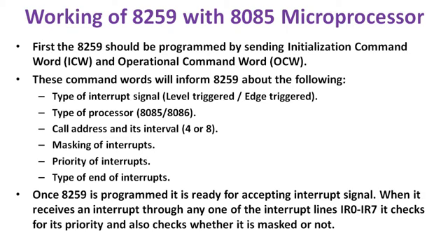And suppose IR0 is made high, then it will again check whether IR0 has been enabled in the mask register or not. If it is enabled, then it will put that into the in-service register, if it has higher priority.